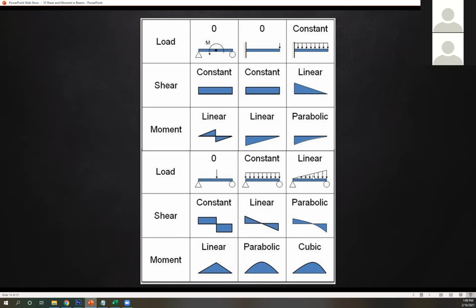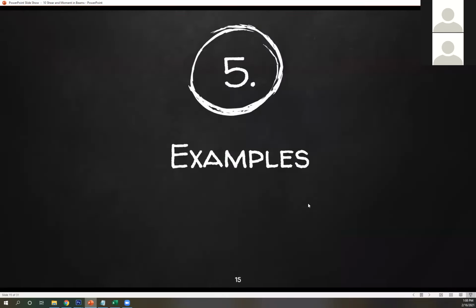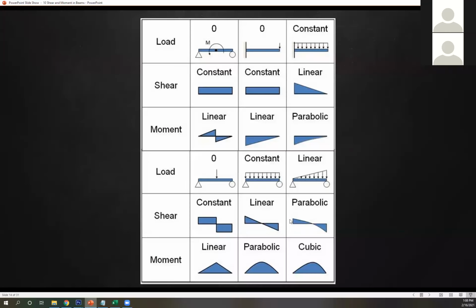This is an example of a triangular load. So again, reaction, reaction. So reaction upward, so you get upward. This is a sloping line, so you get a parabolic line. Okay, so this is downward, therefore downward slope for a parabola, which is again this way, right? So this way, so you go downward until you reach the total magnitude of this load intensity.